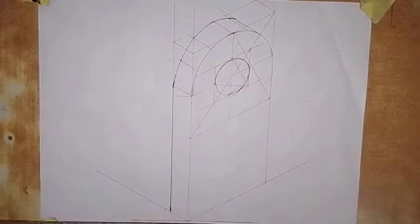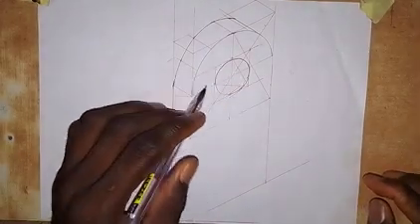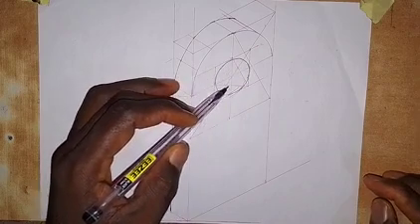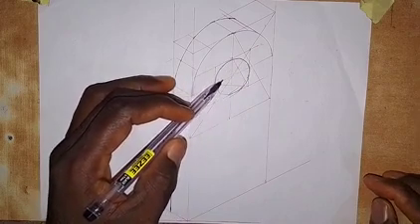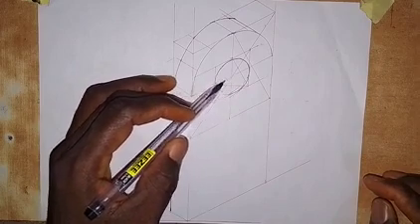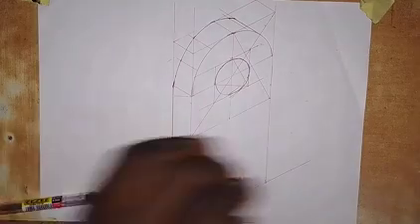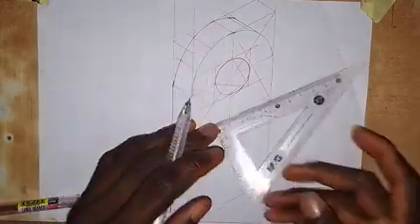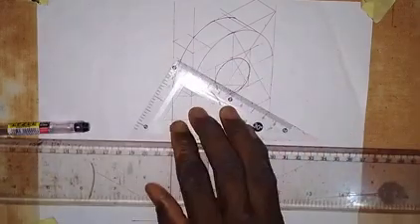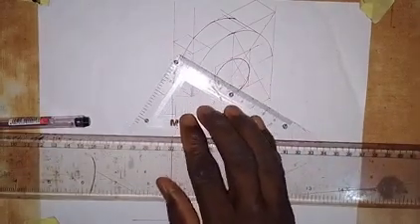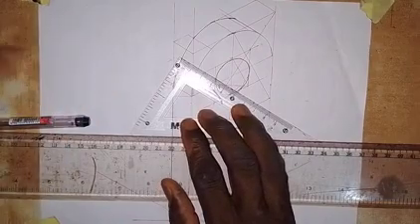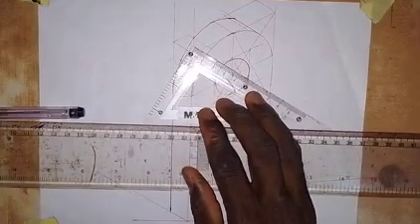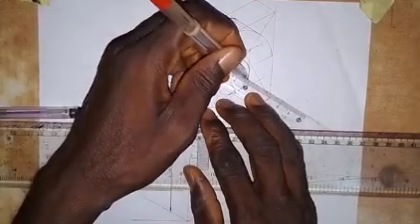Alright, so then the next thing that we are going to do is that for this circle that we have here, because of the diameter that we are given, we should be able to see the other side of this hole on this side. What I mean is this. So for us to see a part of this hole here on this part here, we are going to come to this point. Just take any point here. So draw a line in this direction, and then come to, let's make use of this point. So we draw a line in this direction.